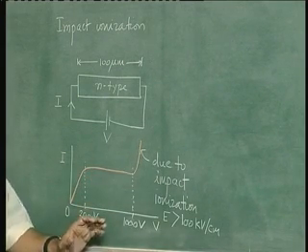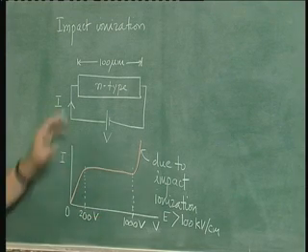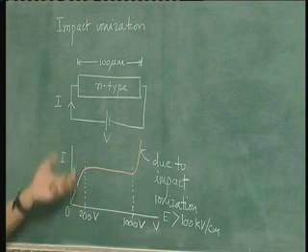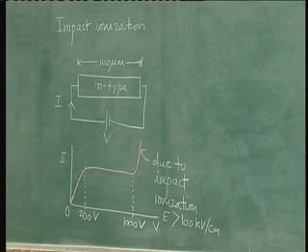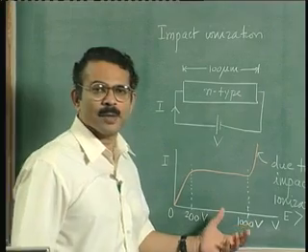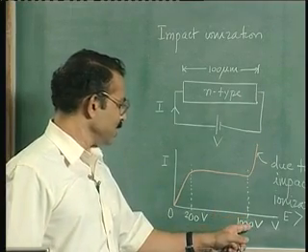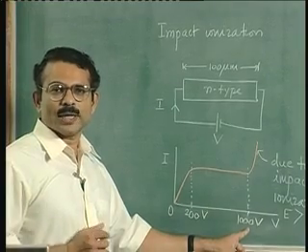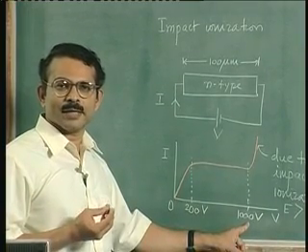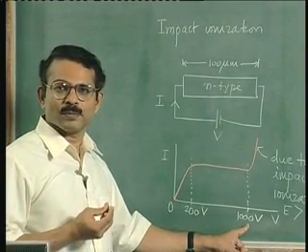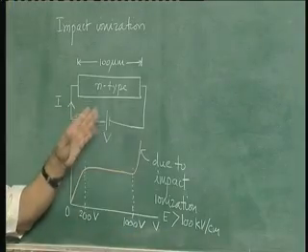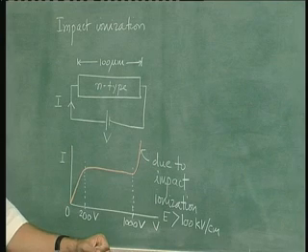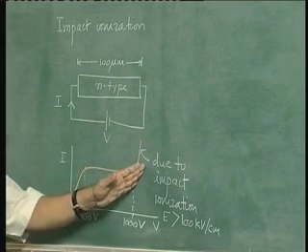Now in practice, please note that the power dissipated in the sample for such high voltages and these currents is so high that the sample will melt unless you do the experiment in a way in which this high voltage is applied for a short time, so that the total energy dissipated is small, and the phenomenon of excess carrier generation due to impact ionization can be observed. So this is one way you can create excess carriers.